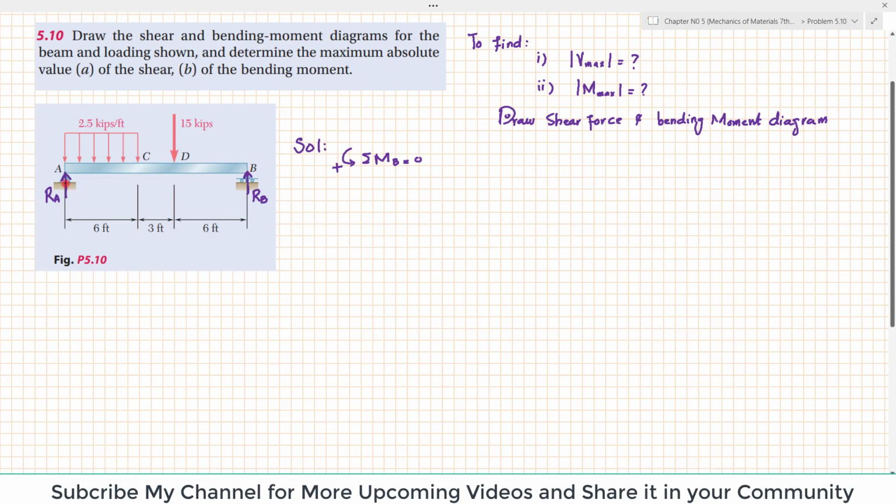The first force producing moment about point B is RA. So RA times the perpendicular distance, which is 6 plus 6 plus 3, equal to 15. Clear? The second force producing moment about point B is this uniformly distributed load, which is 2.5 kips per foot. You have to convert it into a concentrated load. So 2.5, and this load is over a distance of 6 feet.